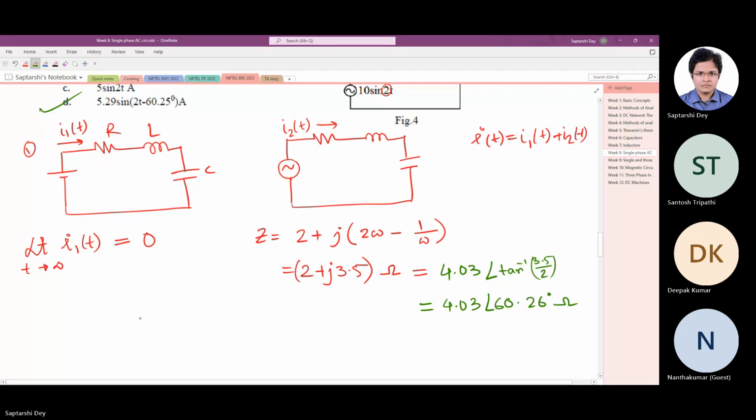This much. Now if I want to write the source voltage also as a vector, so we have written Z as a vector. I want to write the source voltage also as a vector. It is customary to write vectors in RMS, but since we have to again find the instantaneous value, we will write it as instantaneous. But if you are given a question where nothing is mentioned and there are vector voltages and currents, that is RMS, that is the convention. So for this we need not, because we have to transfer it back to instantaneous. So what we do is we take the vector this.